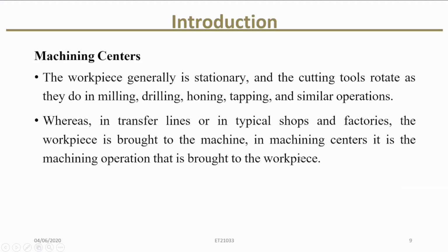What about the working principle when you do this machine operation? In a transfer line or in typical shops and factories, the workpiece is brought to the machine. In a machining center, it is the machining operation that is brought to the workpiece.